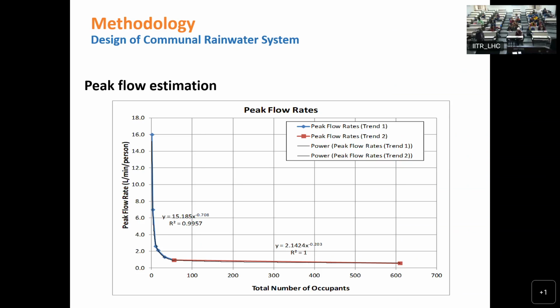That's why you can see over here that when the population is low, the peak is quite high, but as we increase the number of occupants in the population, the peak factor decreases significantly. You can realize that: more sample size, less variation. So in larger cities, the peak factor will be less. Even in a distant town, the peak factor will be further reduced.